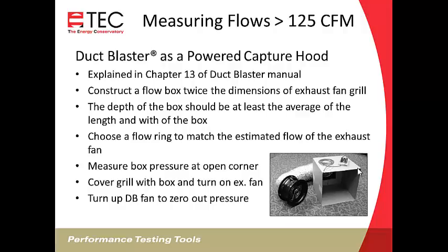So, even with the Duct Blaster fan off, when you put this over the grill, before you turn the Duct Blaster fan on, there's going to be flow through the Duct Blaster, so you'll be getting a flow reading, and as you turn up the Duct Blaster fan and get it to zero, then you'll get an accurate reading.